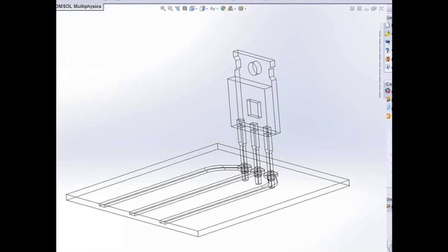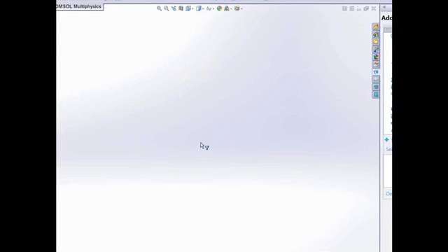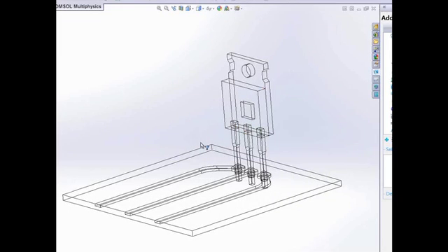Now if I want to start my COMSOL model, I just click the new COMSOL model button in COMSOL, and it takes a few seconds to do this. COMSOL processes the geometry and resolves the domains resulting from all these parts, all these solids that make up your SolidWorks model. And then as soon as that is done, you will get to the model wizard, where you can select the physics. Now it will be the Joule heating in this case.